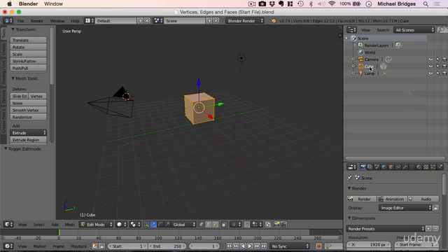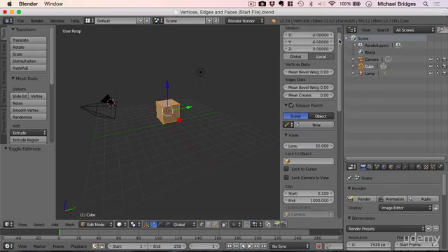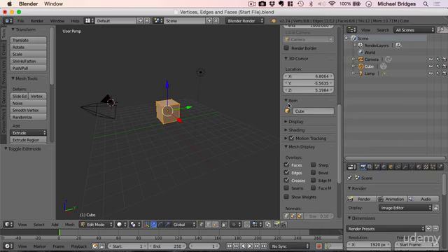You can also see the name of that mesh if I enable the properties pane in the 3D editor, or press the N key. Midway down here, under the item drop down, as you see, it says cube. So you can either change the name here in the outliner or in the properties pane of the 3D editor itself. So if we change that one here to cube 1, we can see it changes in 2 places. I couldn't think of a better name for it. So that's how you name your meshes.